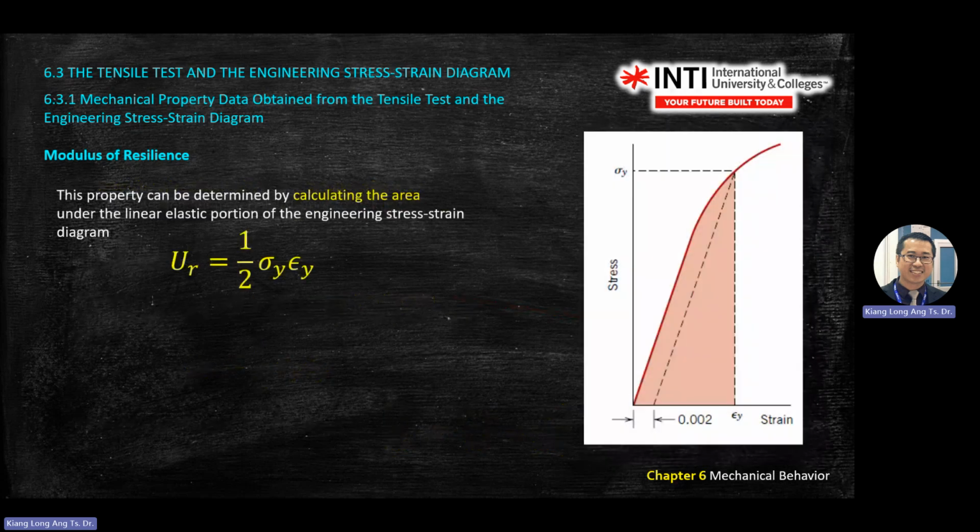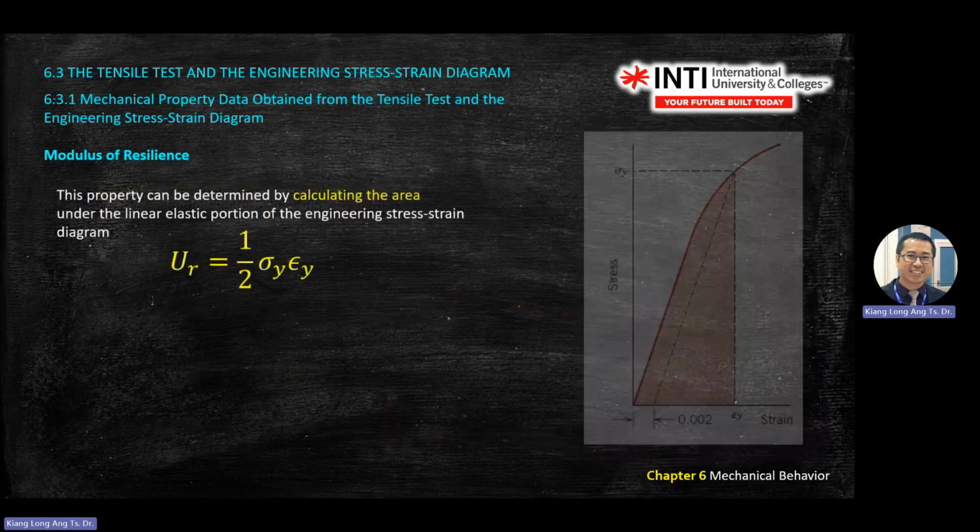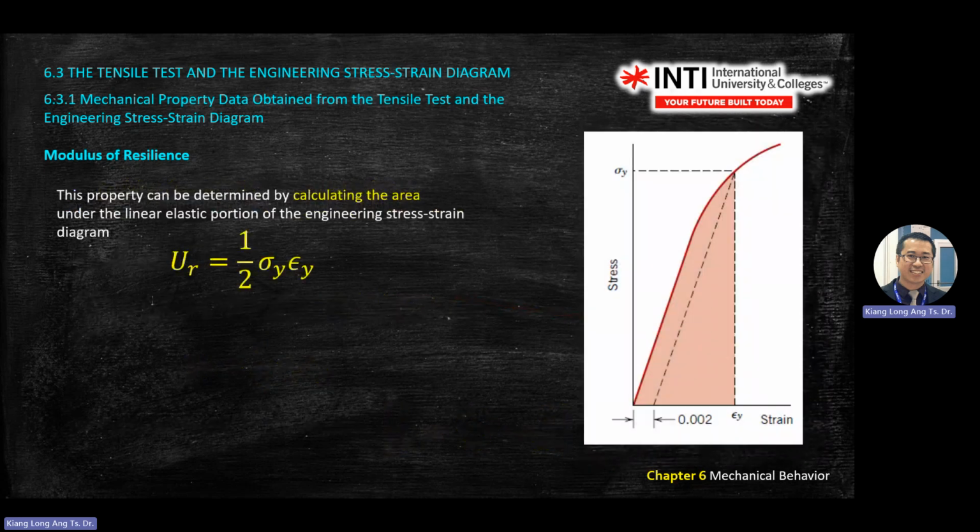Okay, so this just amplifies the highlighted area. Remember, to find the modulus of resilience, you need the U value for strain and stress. To find the U value, you need the 0.2% offset, which is 0.002.